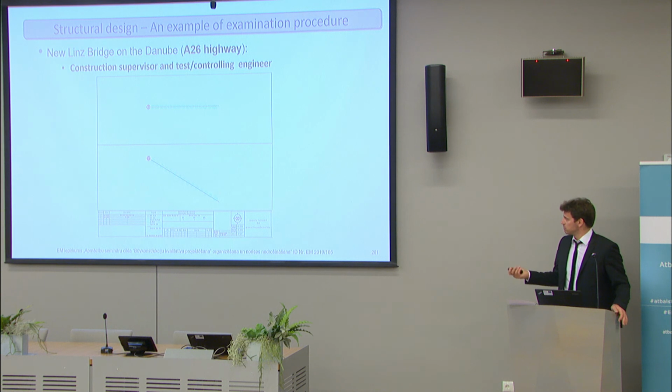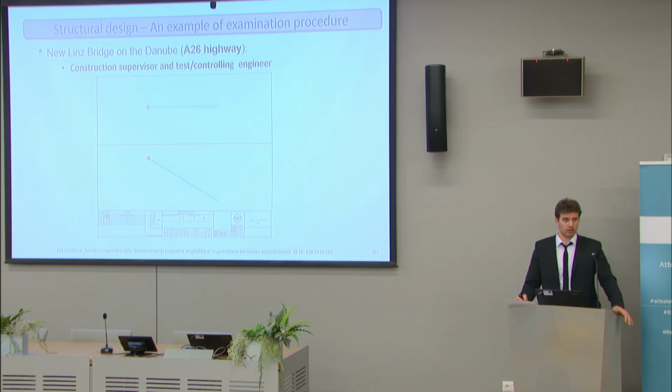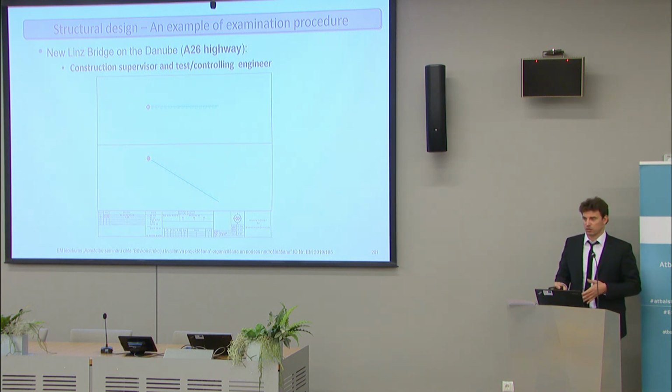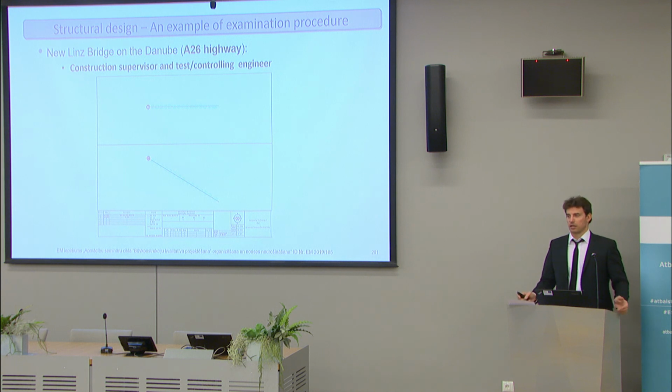These are common, but there are many more reports that you have to prepare every time you drill a borehole. You have to give the position every meter while you are drilling, so that the construction supervision can independently make a verification and put the two graphs one on the other, and if it is okay, it is okay. Until now it has never been not okay, but in case it were not okay, they would probably stop and ask you to re-drill. And this is of course something that should possibly never happen.